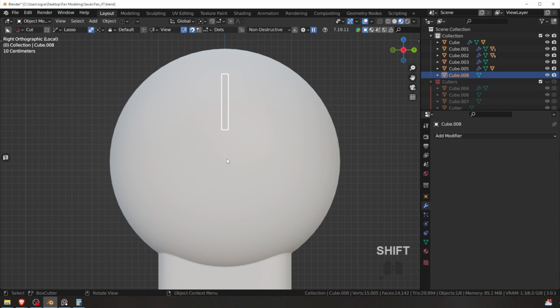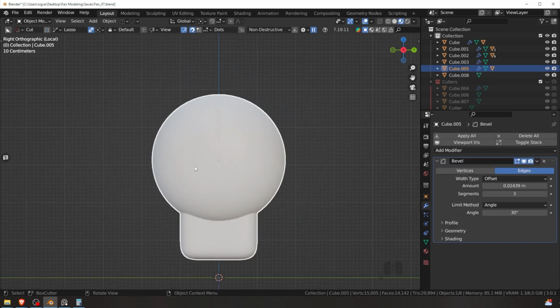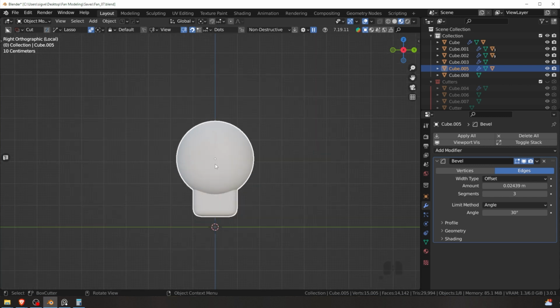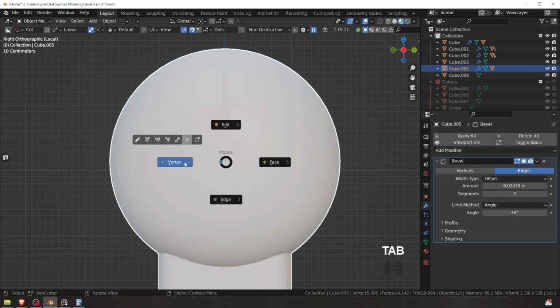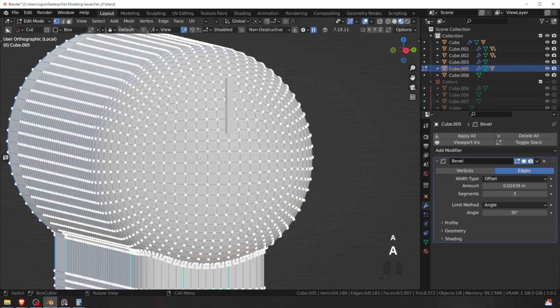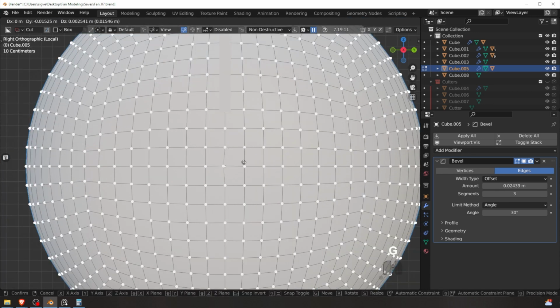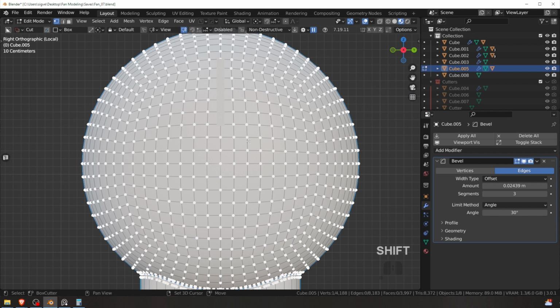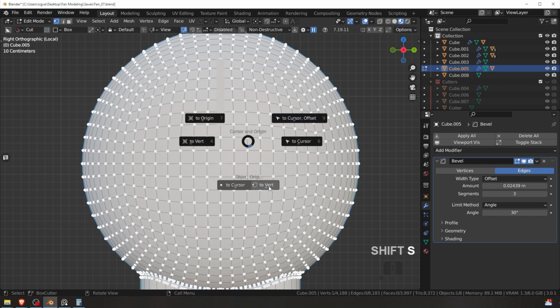We want to rotate around somewhere here, because this is the center of the whole thing, the whole loop, like right there. So how do we do that? Simply go ahead and check where the origin is for this object. In this case, it's exactly where we need it to be. If it wasn't here, you could go into edit mode and find some vertex which is in the center, which is this one right here, and then just press Shift S and object origin to vert.